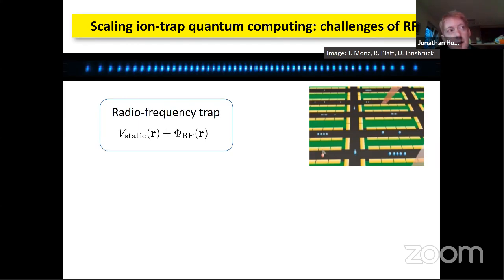I think the thing about those nitride waveguides is that they need to have very low roughness, and so it's actually quite specialized the way that the layer gets put down, and it involves, as I understand it, a lot of heating. So I'm not sure how much you want to do multiple layers of lithography. Now I say that, but it may well be that that's the way of doing the lithography that our foundry uses, and it's not clear to me that that's the only way to do the lithography. I've talked to Sandia people who follow a slightly different approach. I see, but that's sort of a recognized limitation that people are trying to think of. It's a recognized challenge. Yeah, that's right.